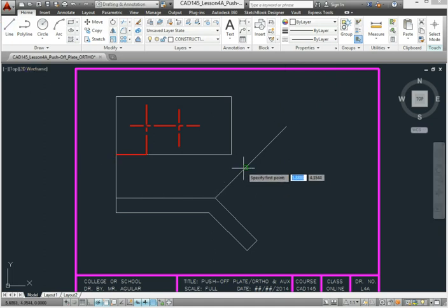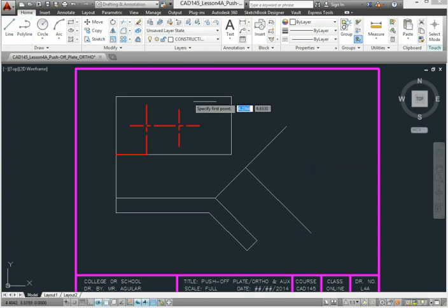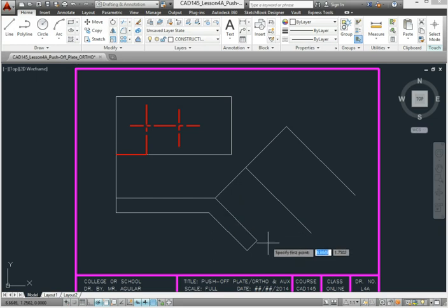Find that endpoint. 45 degrees in this direction will be some unknown length. At this point, it is not important to know what that length is. So we'll just extend in any direction at 45 degrees. Then, to find the end of the drawing, we will project a line from the front view, snapping it perpendicular in this case. So somewhere here will be our auxiliary view.